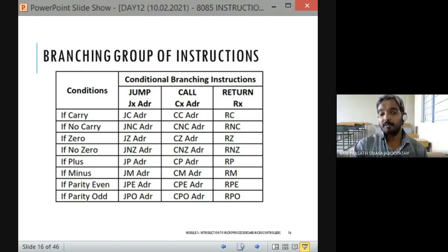So when I write such a for loop in assembly language, I can keep a count in one register, and then decrement that register. If the value of that register is not zero, continue again. So what instruction do I have to use? If it is non-zero, continue, so I have to use a jump instruction. We can see it from this table: jump no zero. Sivakumar, JNZ is the correct answer. Okay, JNZ we have to use.